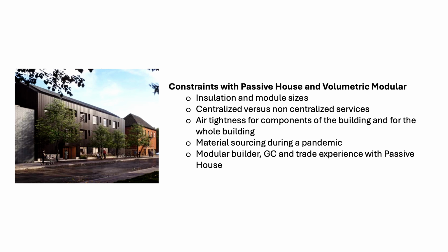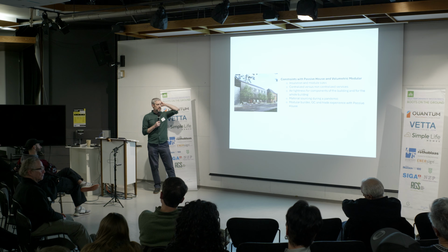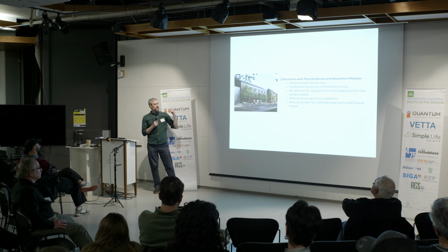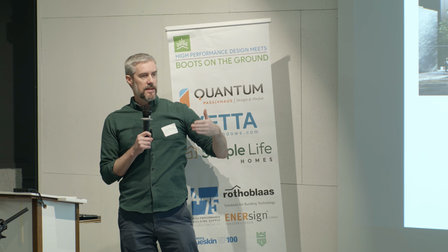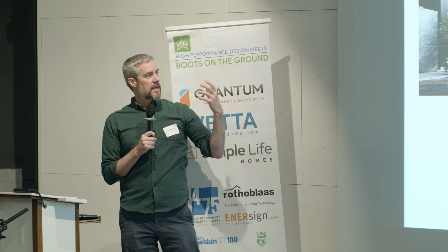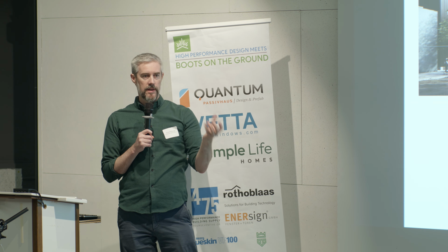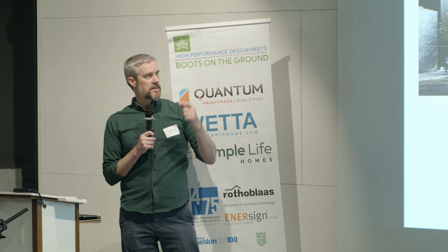Centralized versus non-centralized services. So Josh gave a really great presentation on the benefits of centralized. It works really well on what I'll call a site-built building as opposed to a factory-built building or a modular project. In this instance, we had to do a lot of coordinating of the services such that they could be constructed in the shop and terminated at the corridors. But the suites were all finished, but there was still some interconnections. We had to leave the ceilings of the washrooms open to finish out the connections to the VRF and fan coil units.